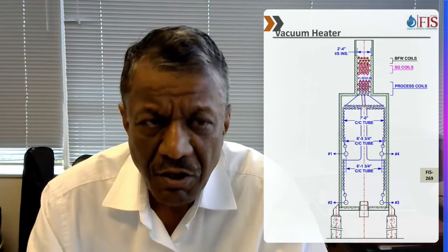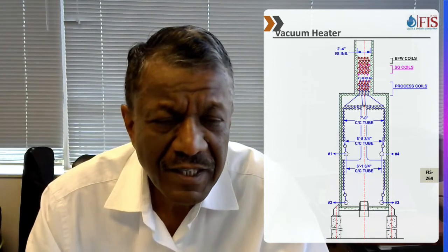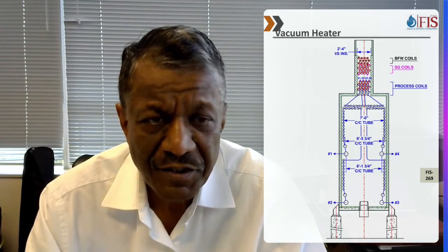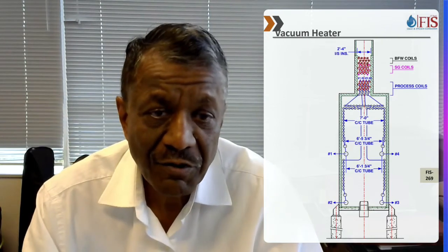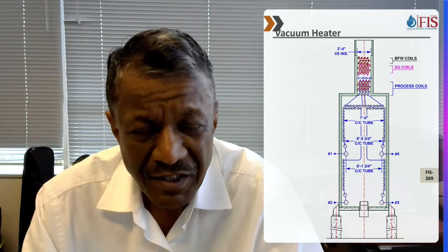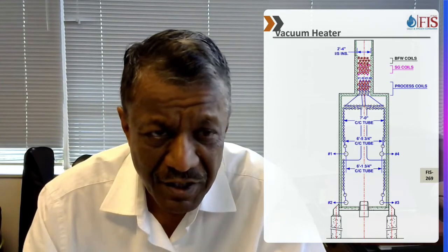Not only coking a lot, the other issue is that the top 2 passes may be getting a lot more heat than the bottom 2 passes, or vice versa, depending on the type of burners. If you have ultra low NOx burners, the top 2 passes will be overheated. If you've got standard burners, then the lower passes will be overheated.